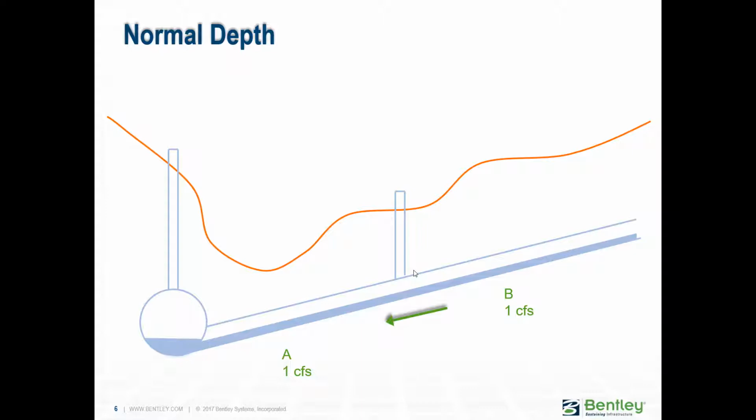When we have flow at normal depth, the steady state equations are acceptable and the conditions are perfect based on Manning's equation. So in this case, you don't really need a dynamic model unless the changes were happening very, very fast. So using a solution like SewerCAD is great.